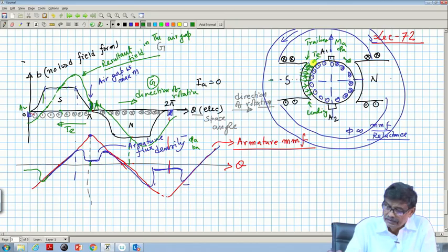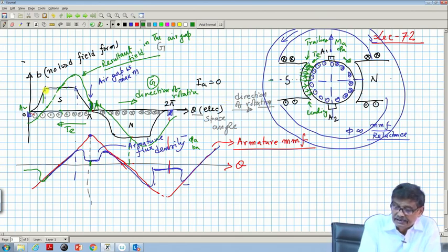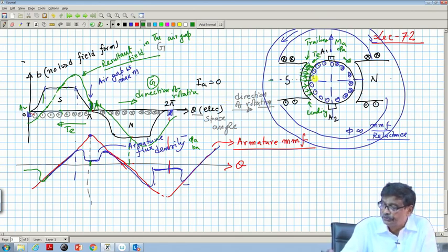So, that will be like this, and it will be here, this side is same as this armature flux along the quadrature axis. So, it is only distortion, that is the main issue here. There is no direct component of armature MMF which really negates in direct opposition to the existing stator field. Okay? That is the whole idea.